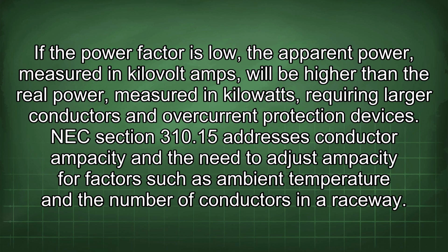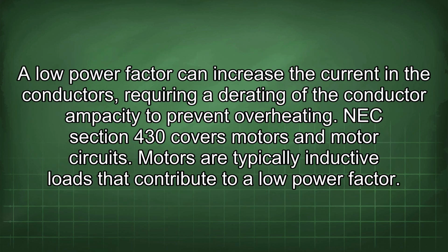NEC Section 310.15 addresses conductor ampacity and the need to adjust ampacity for factors such as ambient temperature and the number of conductors in a raceway. A low power factor can increase the current in the conductors, requiring a derating of the conductor ampacity to prevent overheating. NEC Section 430 covers motors and motor circuits. Motors are typically inductive loads that contribute to a low power factor.